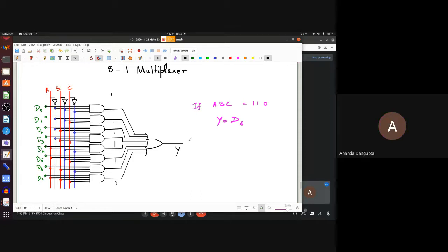Earlier you had only one D which you were directing to each one of the 8 outputs. That is, you had 8 AND gates, each of them 4-input AND gates, 3 inputs coming from the control bits and 1 coming from elsewhere, and you were connecting all of those extra inputs of the 8 AND gates, each and every one of them, to a single input D. So depending on whatever the control bits said, the output would get directed to that.